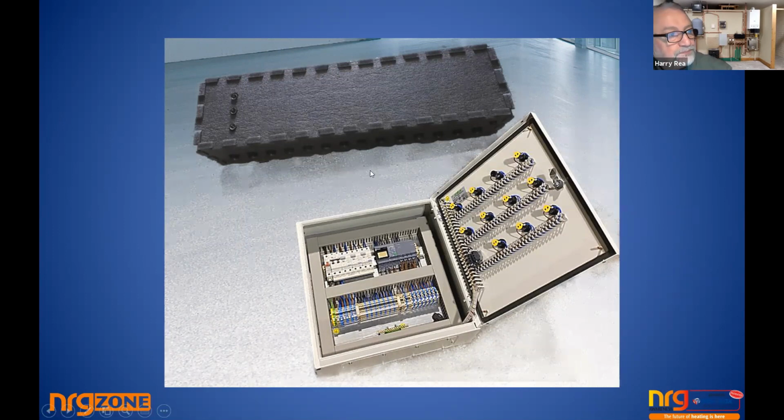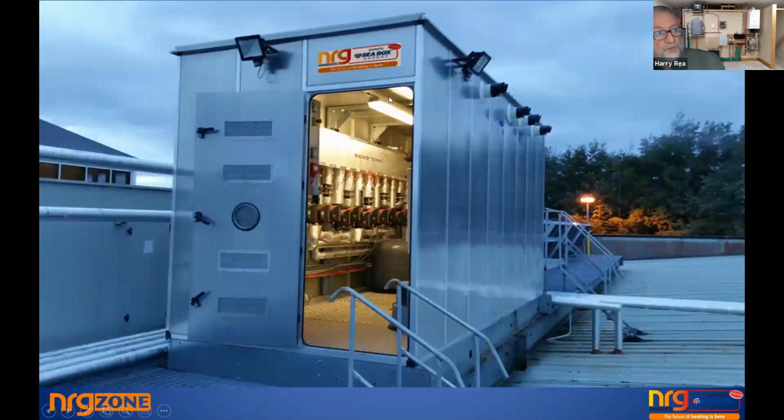And again, I don't know if you know, but we would make boiler house modules. So here there were 4 115 kilowatt boilers on the wall, with some 4-inch pipe behind, traveling on the back, connecting onto the manifold. And then there were 7, I think, zones. That's in a supermarket, on the roof of a supermarket. Everything was prepared to connect onto the pipes, no matter what direction they came. So it was a very, very simple changeover. The job was installed completely with prefab done in less than 3 days on site. On the third day, it was turned on.